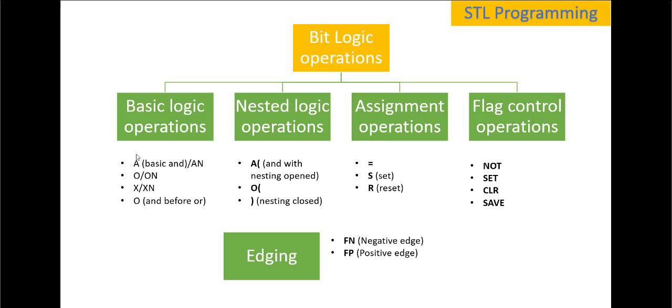This category entails basic AND operation, AND NOT, OR NOT, XOR and XOR NOT. NOT just means that the logic operation is reversed. And then OR, what we call AND before OR operation, which is an instruction that is used to combine AND operations before an OR instruction.